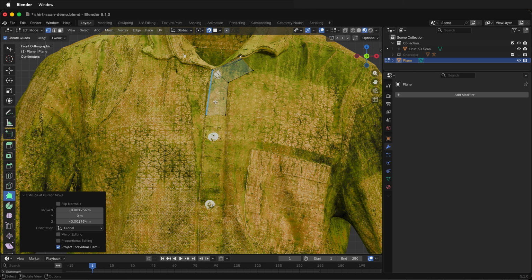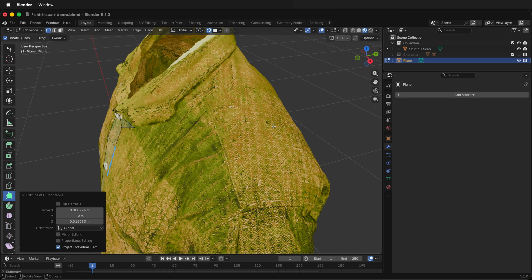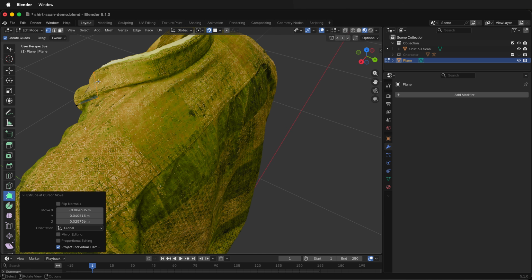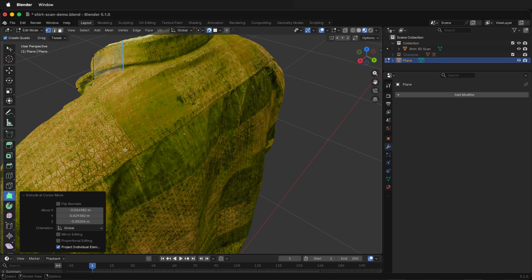As we go around the front part of the shirt, we want to be able to turn with an edge loop here. Then I'll also bring down maybe 3 loops right here. We don't want to be too detailed. We want to keep it generally loose, and then we can always add more edge loops as we go around. Be careful with face project because it really only works with the faces that you can see. So you have to constantly move around and then grab the ones that are there for you to use.